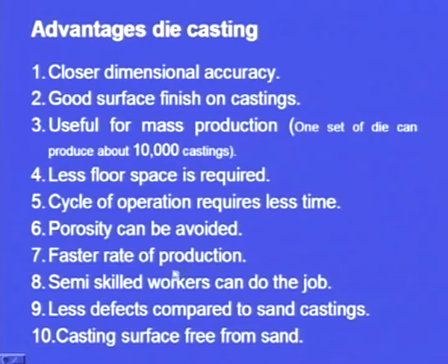So, in the case of the die casting, there is no question of moisture in the mould. We are using metallic moulds. So, the question of porosity or blowholes does not arise, and the rate of production is very high.